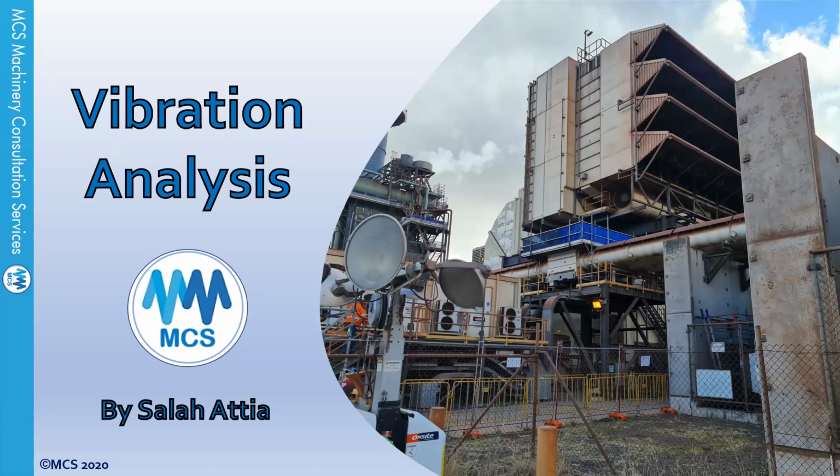C3X in radial direction, pump non-drive end side. It could be for many reasons. It could be misalignment. As we mentioned, if you have certain coupling types, it can excite certain frequencies in your vibration spectrum. So if you have coupling misalignment, it can cause that.